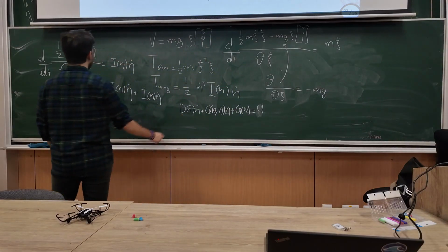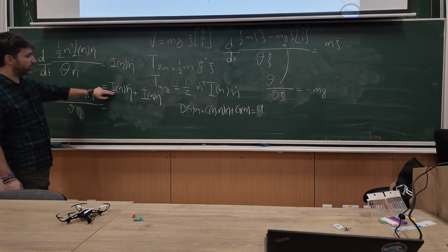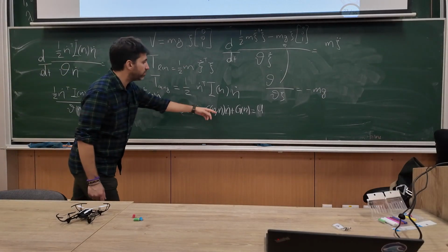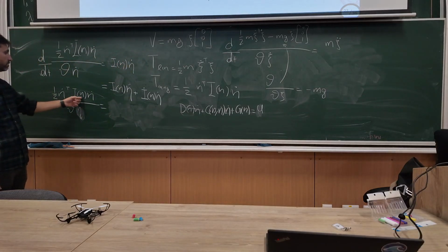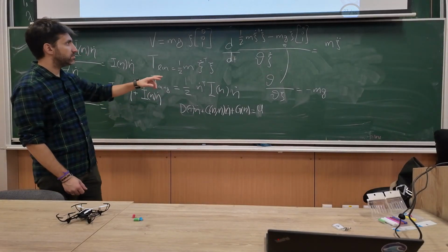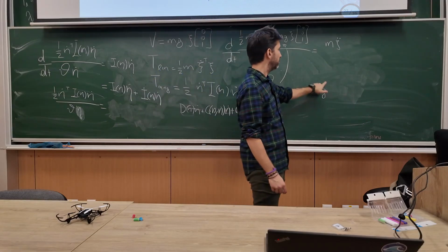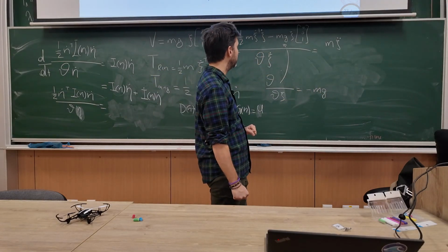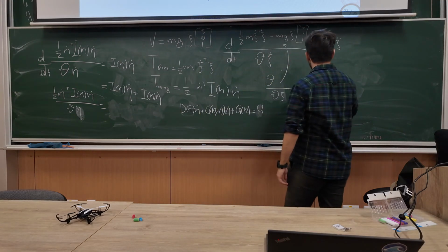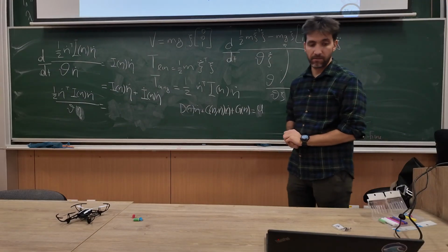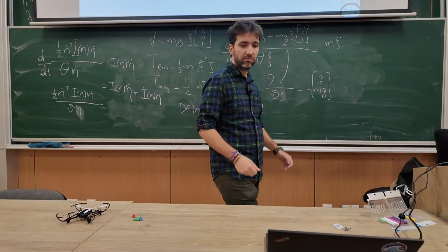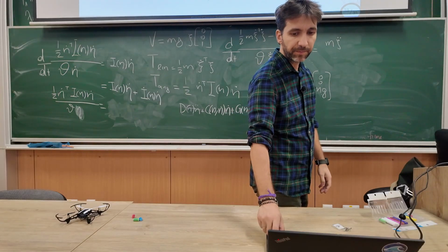The d1 will be what's with the second derivative. It will be the moment of inertia, and you see it's a function of eta dot dot, plus the Coriolis, which is a function of eta and eta velocity, and also from here. And the gravity term is this part, with a 0, 0, 1. So 0, 0, mg. Basically this one. Okay. It's the same form. Different derivation, but in the end we end up with the same thing.